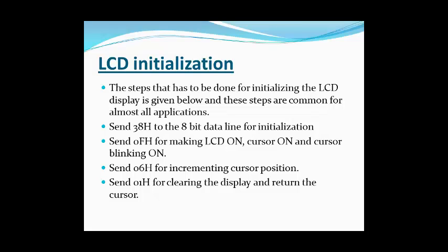We have to send 38H to the 8-bit data line for initialization, and send 0F for making the LCD on. Then send 06 for implementing the cursor position, then send 01 for clearing the display and returning the cursor.